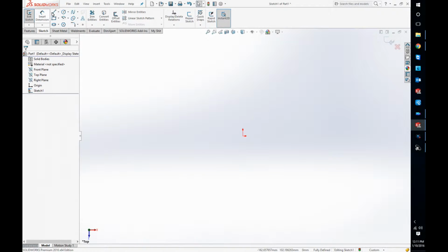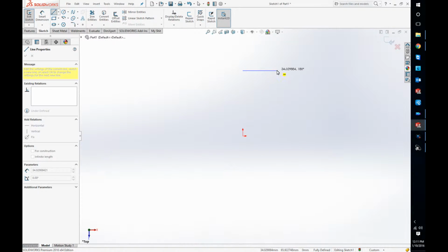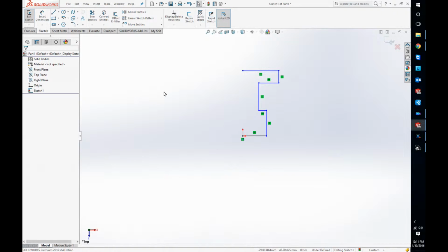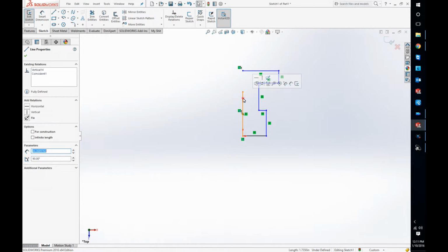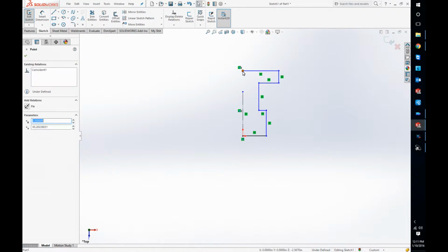Okay, in today's little quick build, we're going to use the Revolve tool to create a simple, somewhat of a pulley. It won't be a fully finalized pulley, but just a simple example of how we can use one. I've done a simple quick sketch out there. I'm also going to put out a construction mirror line, in which case I'll mirror that sketch over after I dimension it. It is always good practice to fully dimension your drawings.